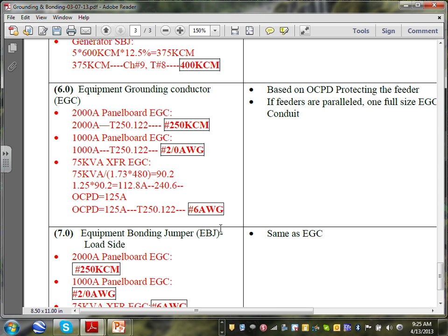I will remind you, you do not need to have an equipment grounding conductor. You could have the EMT conduit as your equipment grounding conductor. Your rigid, intermediate, EMT, busway, bus duct, anything metallic approved by the code. Approved equipment grounding conductor.